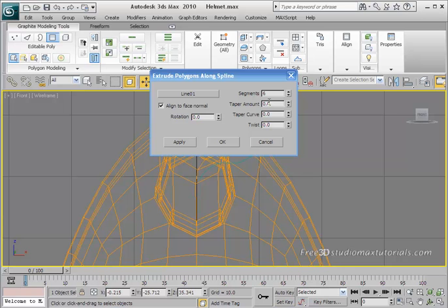Okay, I think I had not set these values. Just click on that and type -0.56, and on twist just type 53.0, and rotation is 0. Okay, now click apply to view your edits to this point. Continue to use the dialog controls to shape your horns, then click OK when you're done. You just apply this.